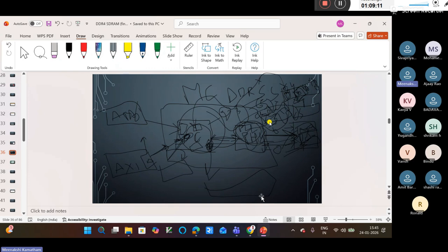Yeah, where did we start? Yeah, the data. See here, the data present in that DRAM that we've written comes back into the PHY block. After the PHY block, it comes into the controller. Then the controller changes that physical data into logical data. Here we have the AXI monitor.